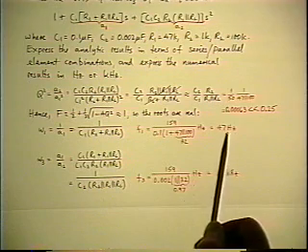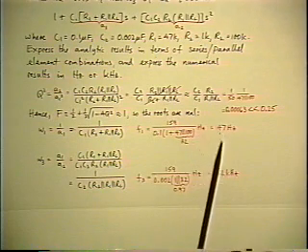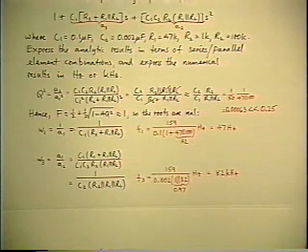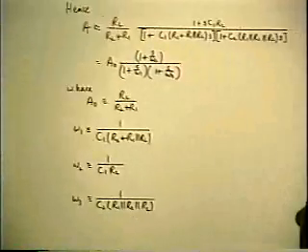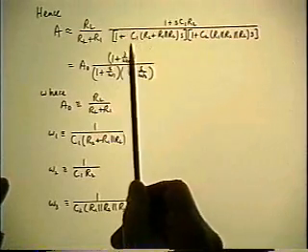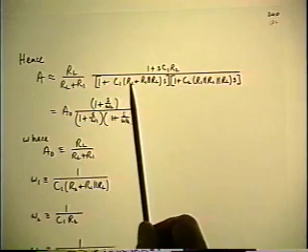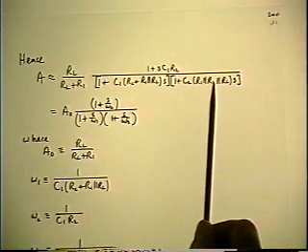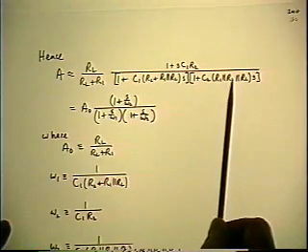The result comes out, the two roots are 47 Hertz and 82 kilohertz, which verifies the two roots are not only real, but well separated, which is the consequence of a very small value of Q. So here's the assembled results. This is now the factored quadratic in the denominator, where these are the approximate real root factors, assuming the f is equal to 1. And you see, no radical sign.